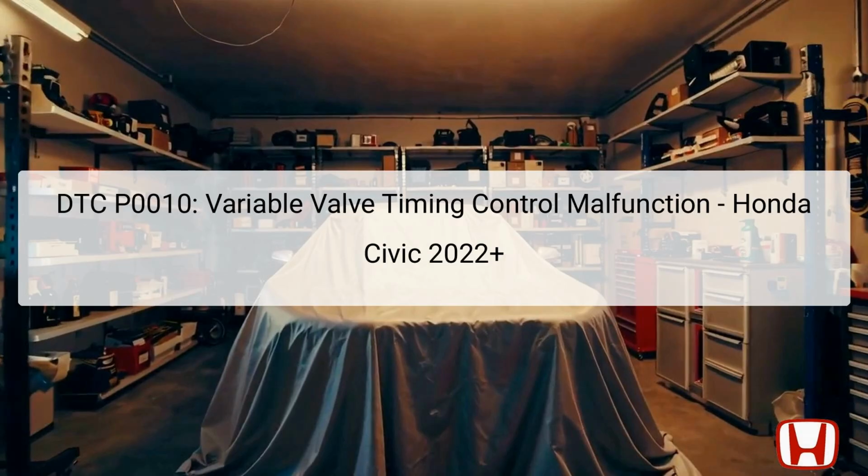If the commanded current to the solenoid does not match the actual current, meaning there's a significant discrepancy in performance, the Powertrain Control Module, PCM, identifies this as a fault and sets the Diagnostic Trouble Code, DTC P0010. This code may lead to performance issues or increased emissions if not addressed. Proper diagnosis will involve assessing both the solenoid's condition and the associated circuits, ensuring all components are functioning as intended.